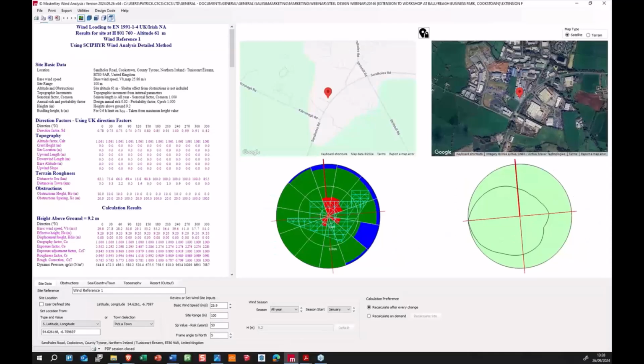The first polar graph displays our roughness category, indicating your structure surrounded by 30-degree segments, and the distances to sea in blue, country in green, and town in red. Roughness is about surface obstructions that impact how wind slows down near the ground, for example, buildings and trees. And fetches are displayed radially from the site on a logarithmic scale. If you look at the first line there, that's 1 kilometre from site. If you look at 10 kilometres there, we do get a logarithmic scale all the way to 100 kilometres here.